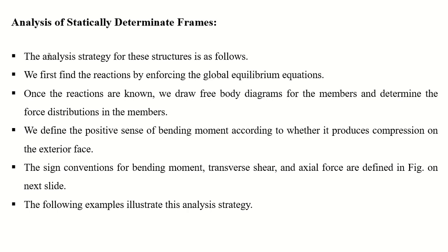What are the analysis steps of statically determinate frames? The analysis strategy for these structures is as follows. We first find the reactions by enforcing the global equilibrium equations. Okay, first you have to find the support reactions. This is your first step. Once the reactions are known, we draw free body diagrams for the members and determine the force distributions in the members. Okay, so after reactions, you draw the free body diagram for each member and then determine the forces in the members.